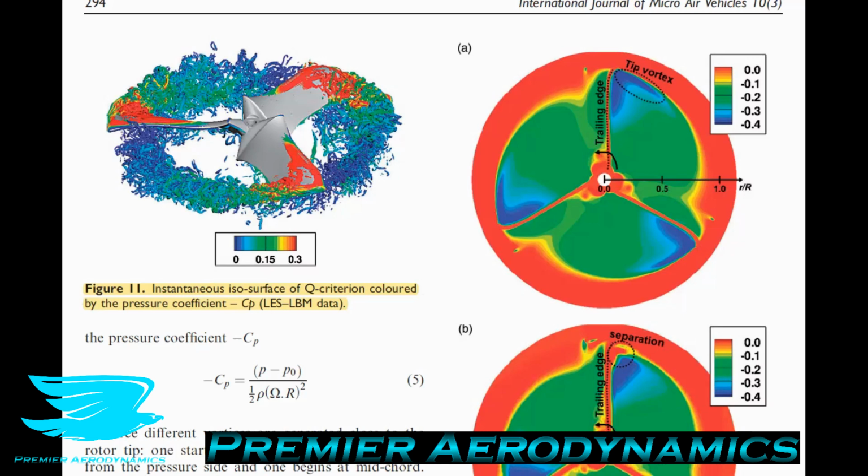So the breakdown of these 3 vortices starts close to the trailing edge due to the recompression. These vortices also merge with the vortex due to the separation of the suction side boundary layer close to the tip. The mixing process between the different vortices produces turbulence that impacts the following blade, located in the left part of the figure. So we can see it here.